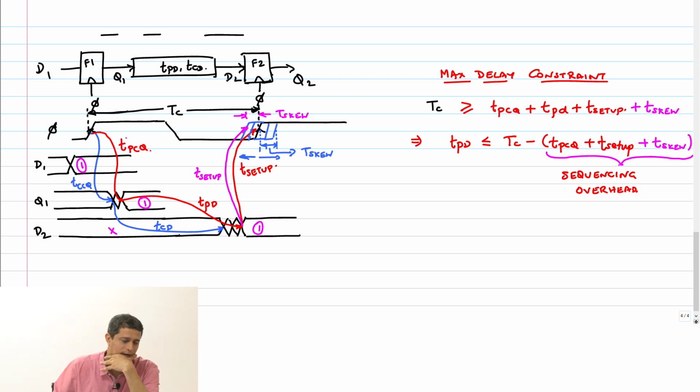Between any two clocks, right? Therefore if I consider T skew here once, I'm done, because I've considered between any two random clocks this is the maximum number. You could divide it as T skew by 2 here and T skew by 2 there, it doesn't matter, it's just one counting. So what he's saying is the T skew definition is the worst case difference between any two clocks on the leaf nodes. That is T skew. Okay, so that we have taken care of here.